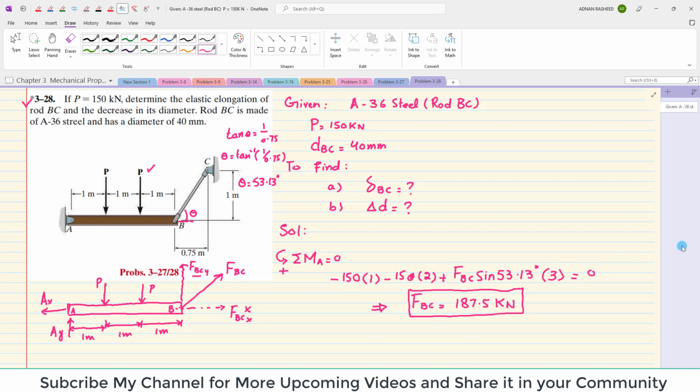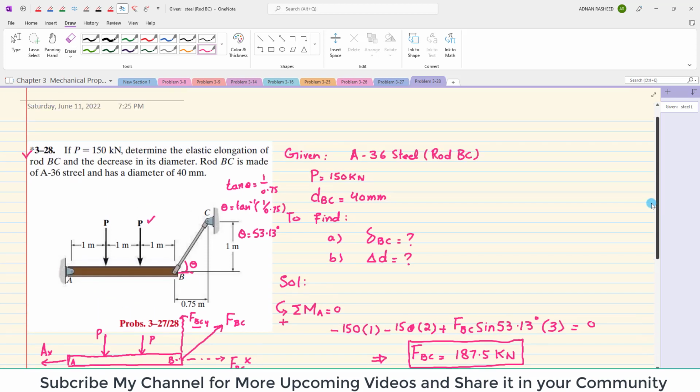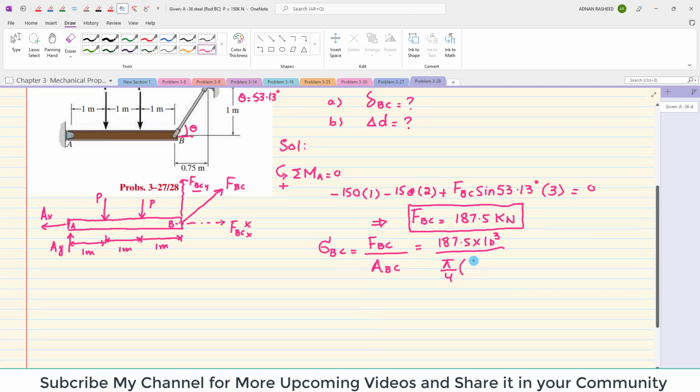Now you have this force, you can find the stress in rod BC. The stress in rod BC is equal to the force in BC divided by the area of BC. The force in BC is 187.5 times 10 raised to power 3 newton, divided by the area, which is pi by 4 times the original diameter of 40 millimeter, in meter 0.04 meter, squared. When you solve this, you will get the stress in rod BC equal to 149.21 megapascal.